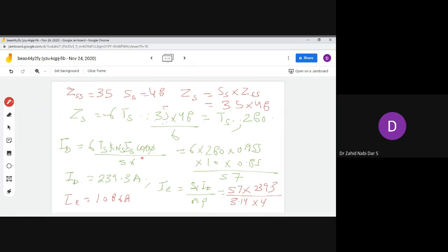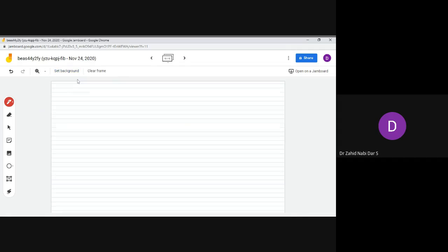So now you have to see the rotor resistance. Now the rotor resistance, that is the resistance of each rotor bar, RB. This is RB would be rho LB by AB. So rho value is given 0.02, LB value is also given 0.12, AB is given 9.5 into 5.5. So you get this around 46 into 10 power minus 6 ohms.